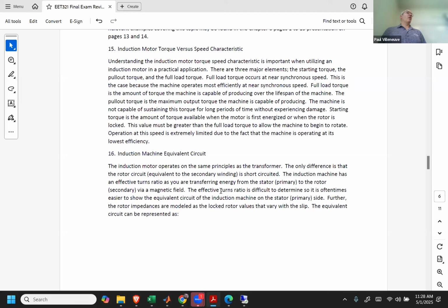That's one way if you're trying to get some input, you can just go ahead and build your torque versus speed curve. Or if you want to get some specific parameters like pull-out torque or starting torque, you can make some adjustments, if you will, or you can get some Thevenin equivalents, and you can do those calculations that way. It's just that you have to make some assumptions and simplify things down to do it, but you can do it that way.